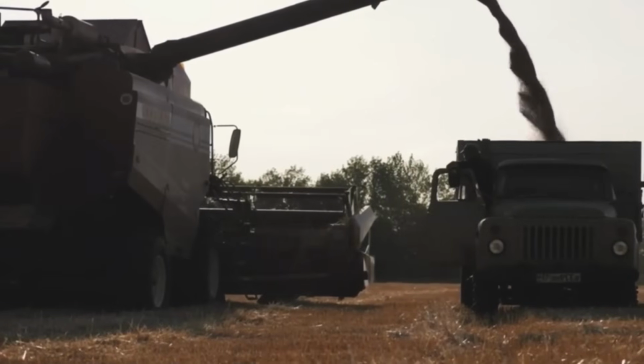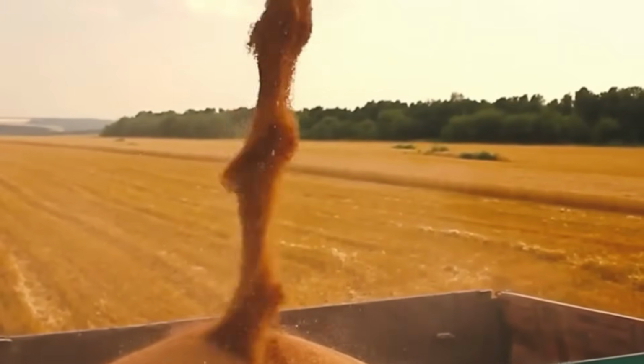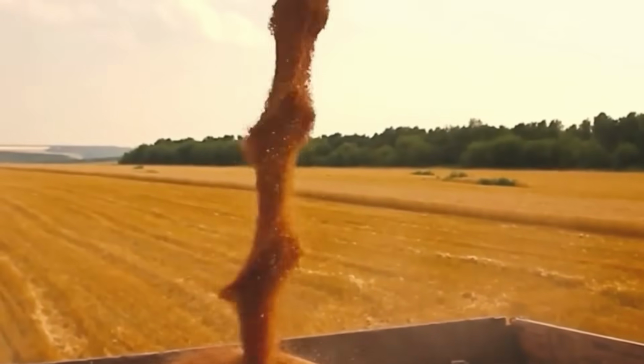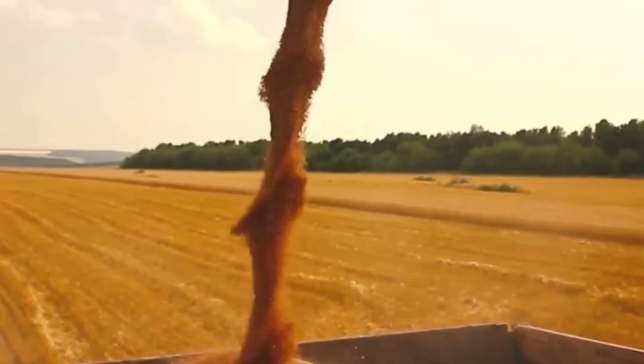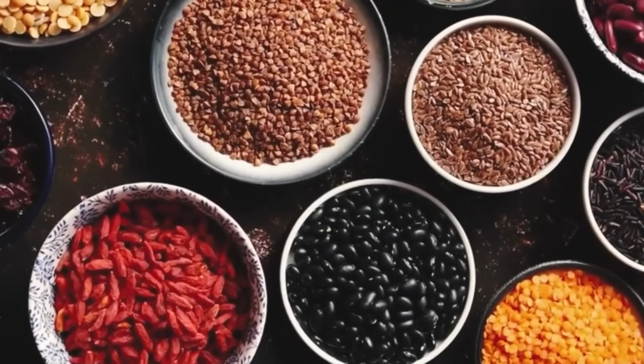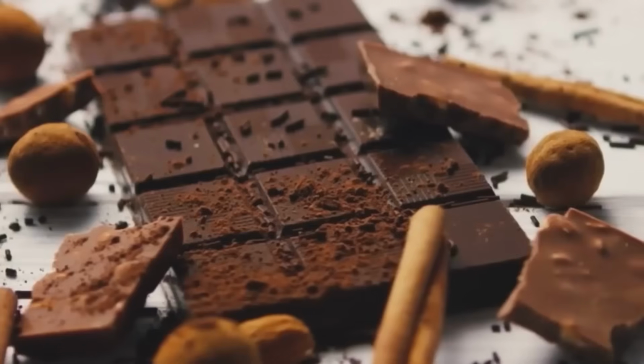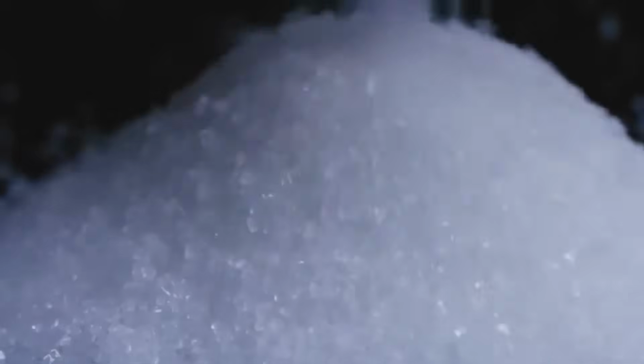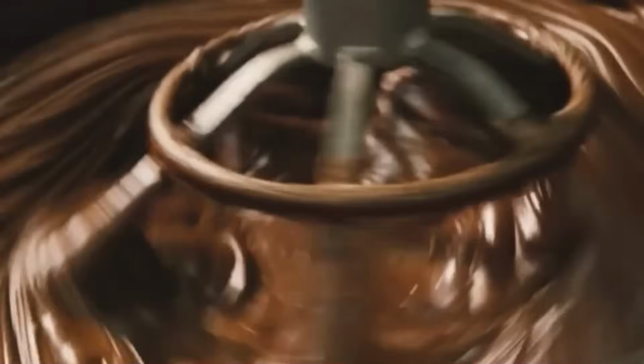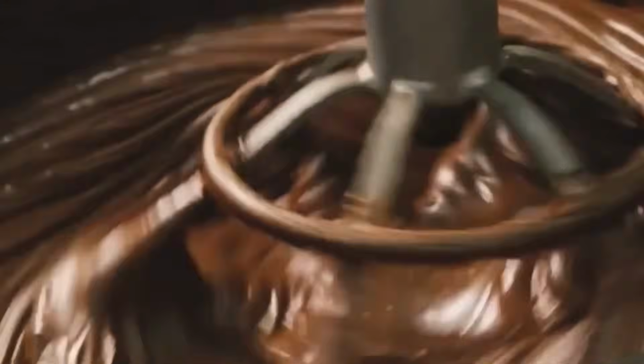0.3 grams. To prevent air entrapment during deposition, the filling nozzle retracts during injection at a synchronized rate, matching the filling viscosity and back pressure. Cream flow is assisted by low-pressure nitrogen to maintain a consistent stream and eliminate pulsing. After filling, each shell passes through a cooling tunnel maintained at 10 to 12 degrees to solidify the fat phase of the filling and prevent oil migration into the wafer wall.